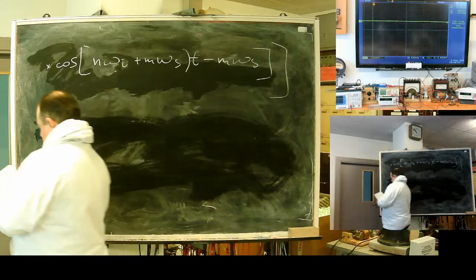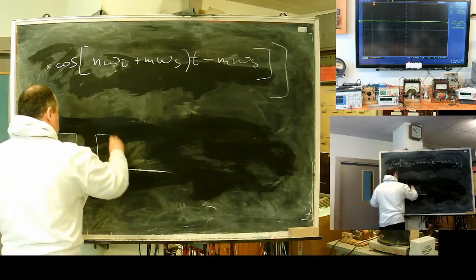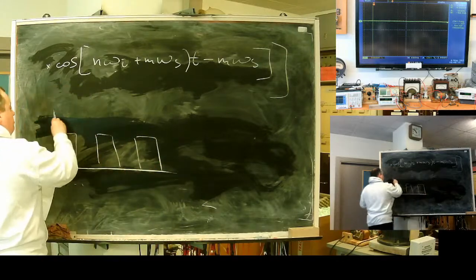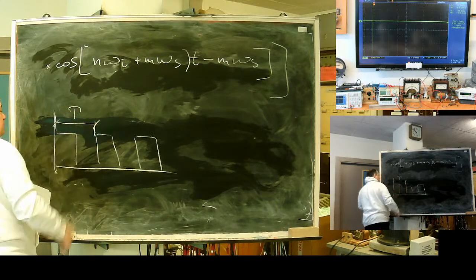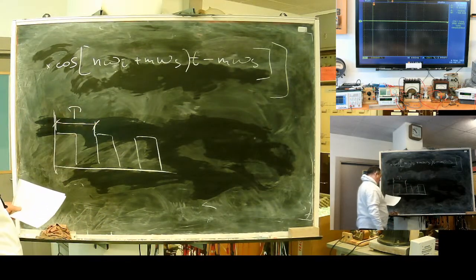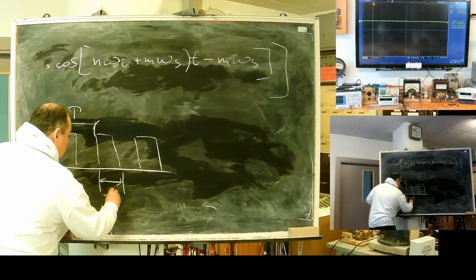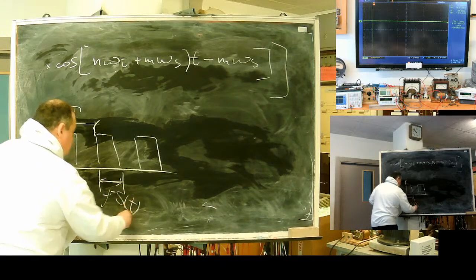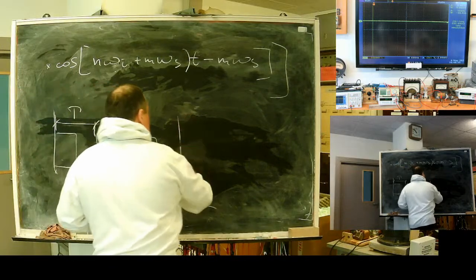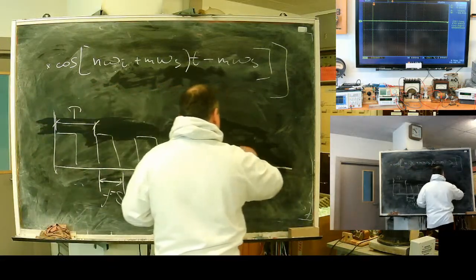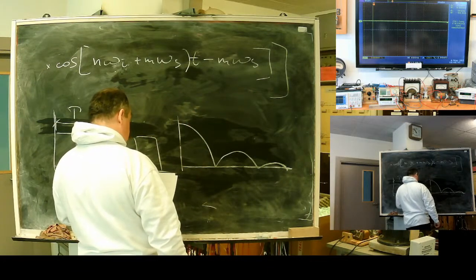So, if you have a sequence of the pulse with the repetition period of time and its width being a function of signal, you will get a spectrum like this, borderline, something like sine x divided by x.